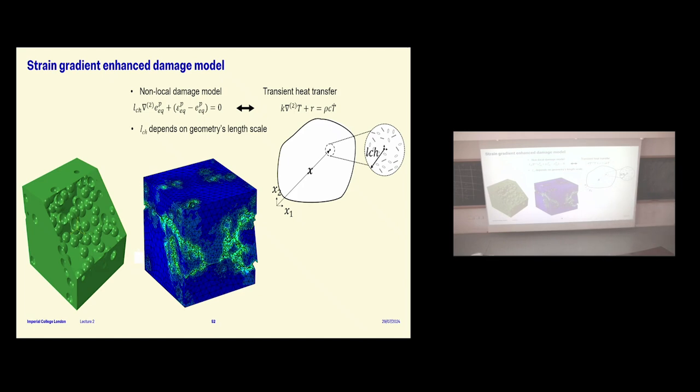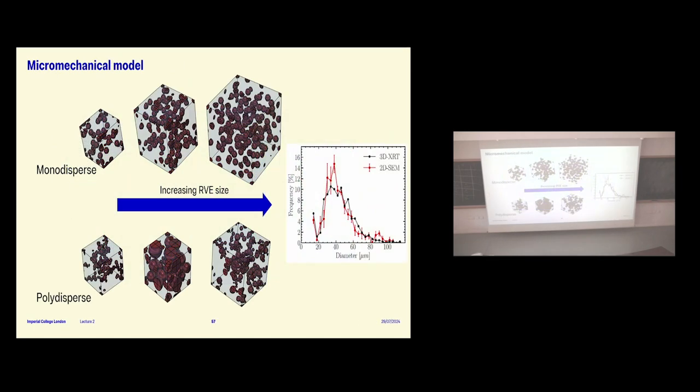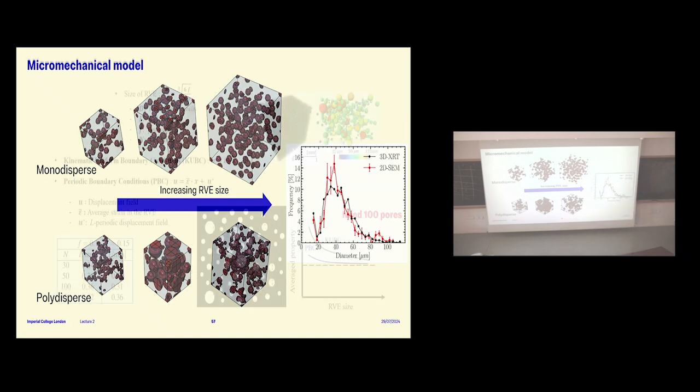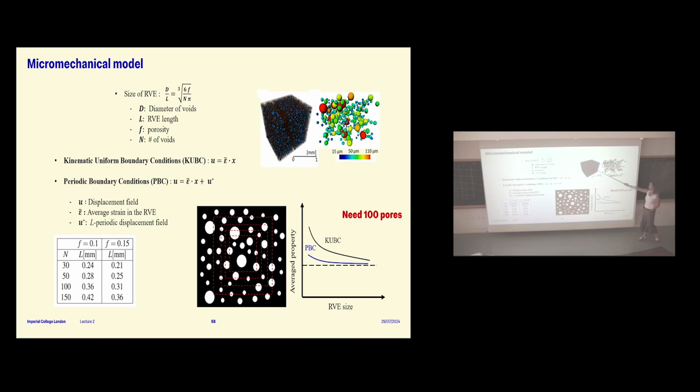Okay, so we did various things. Here we took the mean of the diameter, and we had models which had all the same size little gaps. And down here, we tried to reproduce the whole particle distribution with different sizes. So monodispersed means the same size, polydispersed means different sizes. And we also have, remember, the X-ray tomography, such that we could model it exactly as it is. We got this geometry, and we can fit it inside the finite element models.